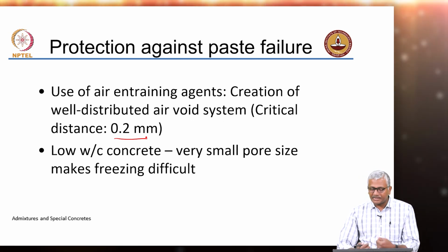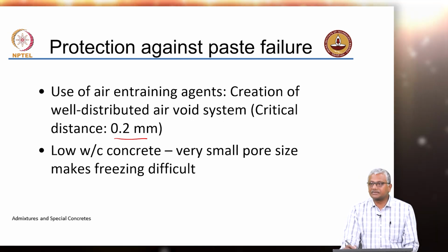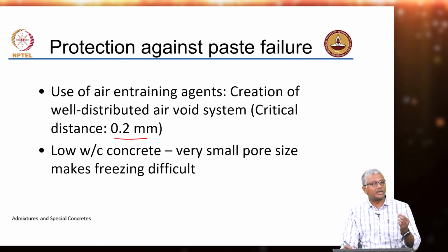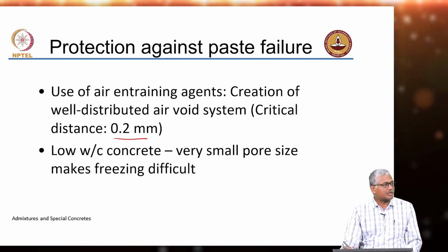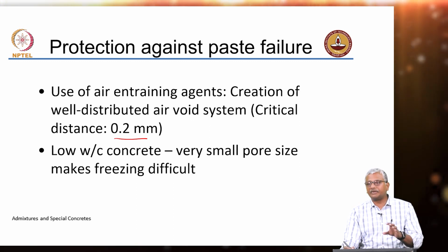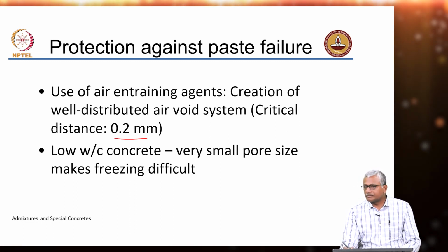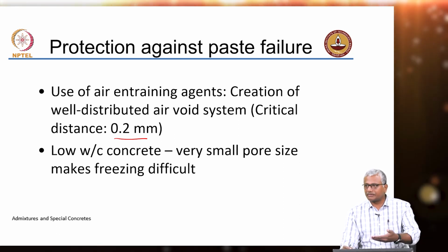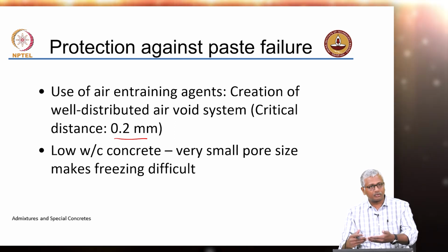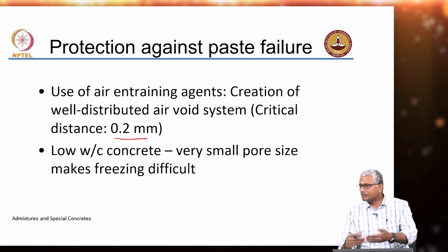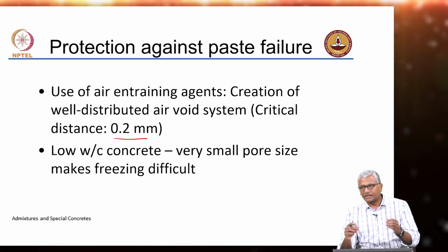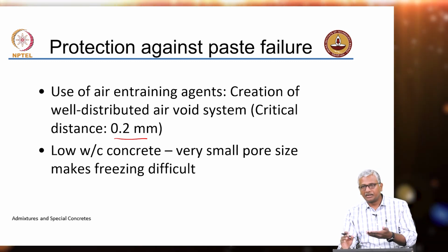This is an ASTM test again. So, this test method basically tells you how to do an air void analysis inside your concrete. That helps you estimate the total air as well as the critical distance between the air voids. This is a very painstaking test. You need to sit in front of the microscope for at least 3 to 4 hours to really go through even one sample, and the sample has to be well polished, right?